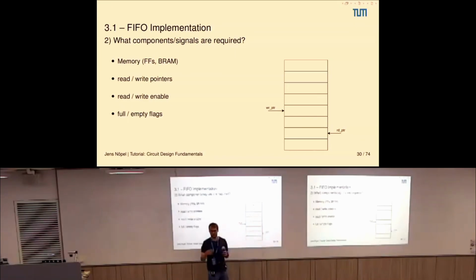Maybe in the meantime, module B, the receiving one, wants to read some data. So first it reads data from where the read pointer is pointing. It reads that data out, increments the read pointer, then it reads out this one, and increments the read pointer.